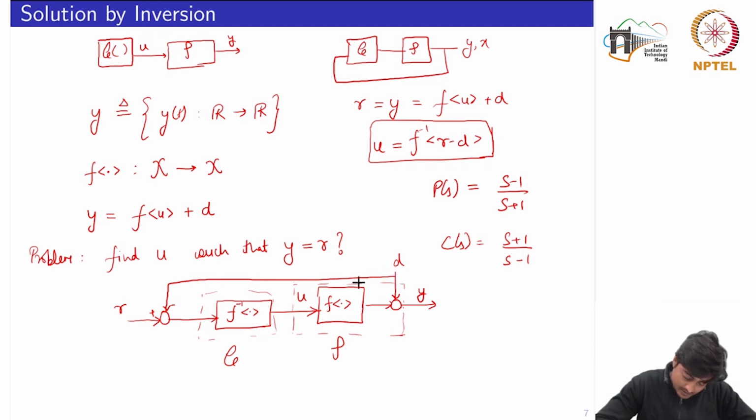Second, for computing the output of the controller, it requires the information of the disturbance variable, because the disturbance variable is being fed back also to compute the control signal. In usual practice, we do not have the availability of this disturbance variable, so it is quite difficult to compute the control signal.